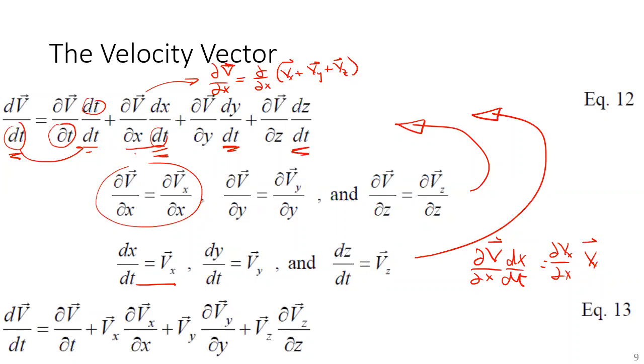So these are all convective accelerations. What's this one? It's a local or normal acceleration. What does that mean? For the first three, the convective accelerations, we're talking about taking a snapshot in time and telling me how the velocity changes as you move through space.